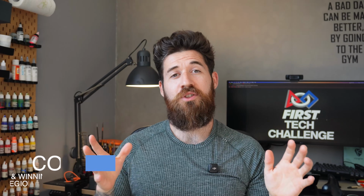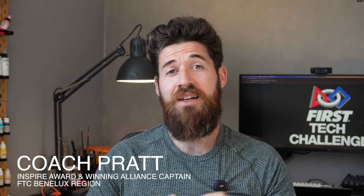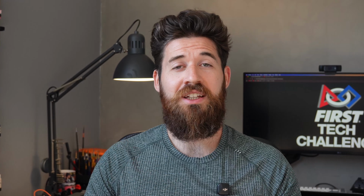Coding a Mecanum drive is a fundamental step for most FTC teams, but getting it to drive intuitively is a major hurdle for a lot of them. By the end of this video, you'll have a clean, reusable Java class for your Mecanum chassis, and you'll understand how to implement both robot-oriented and the far simpler field-oriented control. I'll also explain what both those terms mean if you have no idea what I just said.